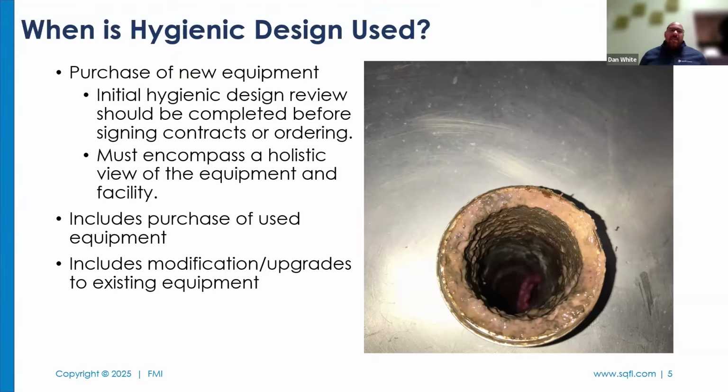The other one is that, when it comes to hygienic design, especially welding, it's imperative that somebody's actually qualified to do that. I grew up on a farm. I can stick two pieces of metal together really, really well. However, I wouldn't consider the welds that I do to be hygienic in nature. So if you don't have somebody in your facility who is capable of doing a full penetration weld with a smooth surface on the inside, outsource it. It is far worth the extra money to get somebody who's qualified rather than put something in line that may or may not cause contamination later on.